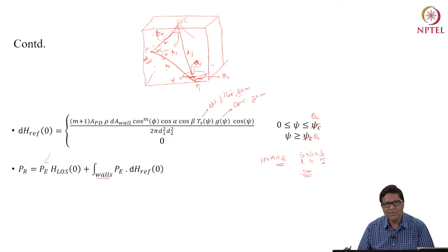And the delay will be very small, a few nanoseconds. So if you back calculate, it will give you a bandwidth of about 100 megahertz. Whereas the devices used here, the receiver and transmitter, generally have about 20 megahertz. A good device will have a response something like this, the normal LED normally used in the room for illumination. So basically, it sees a flat channel. It is not a frequency selective channel. So that is why DC gain is sufficient to represent the optical wireless transfer function.